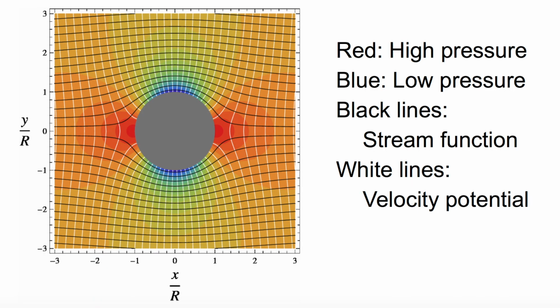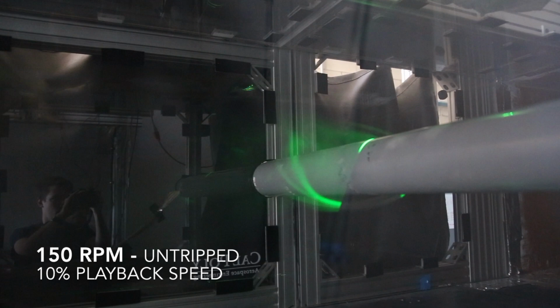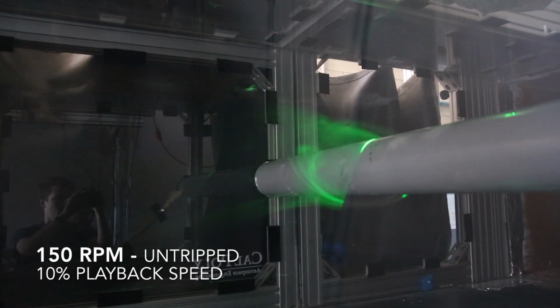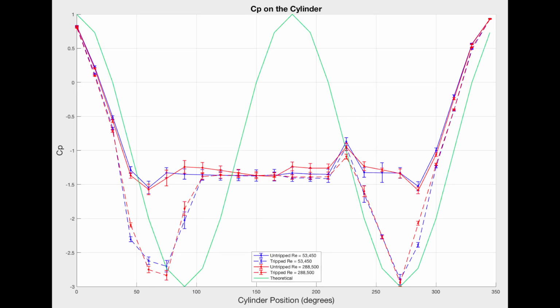Along the forward face of the cylinder, the pressure should be highest at the stagnation point and should drop as the flow accelerates to twice the free stream velocity at the top and bottom, and then it would decelerate, causing an increase in pressure as it traveled to the back of the cylinder. However, as the flow reaches the top of the cylinder, the pressure remains relatively low due to the vortices caused by the flow separating. It can be seen in the plot of CP and CD that the flow becomes disconnected at around 45 degrees from the stagnation point at both 11 and 26 meters per second.